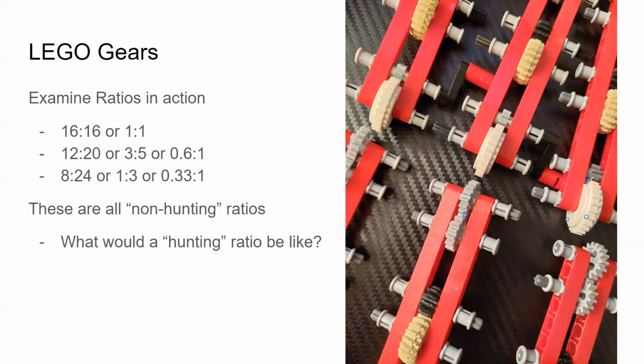So this bad tooth on here would hit 3 different companion teeth on this gear, and it would cause problems, but it would be distributing the damage that it causes. So it would take longer to get to a catastrophic point on there. That makes the gears last longer. They can be more tolerant to damage and they last longer that way when you're not repeating the companions like you are on this 1-to-1.